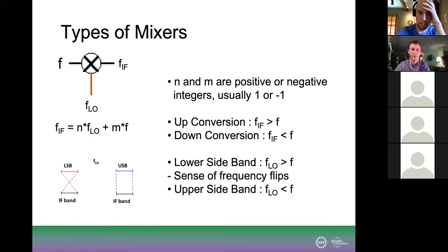But when you do observe and when you do mix in the signal, you actually get both sidebands, an upper sideband and a lower sideband. The GBT, we generally reject the sideband that we don't care about. It's effectively filtered away. So we do single sideband observations. A lot of millimeter telescopes, especially, use the SIS mixers where they actually mix before they amplify. And a lot of those are dual sidebands, meaning you get both the upper and lower sideband within your IF.